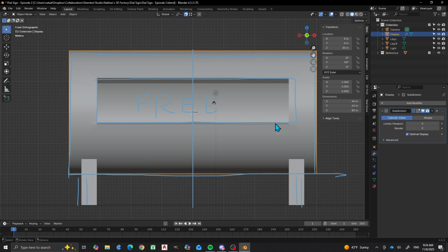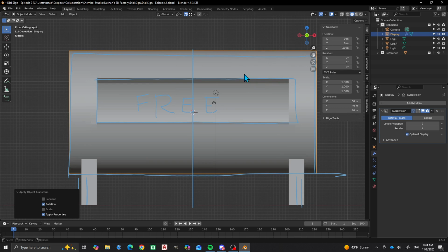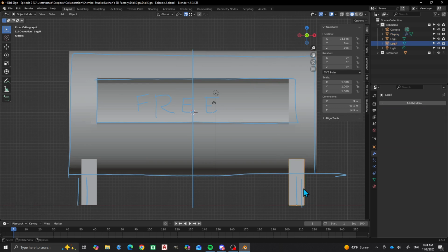Now I'll get a basic shape for the drum. So it'll be another cylinder. So this cylinder right here. Oh, and you'll also see that this has a 90-degree rotation. I don't want that. So I'm going to do Control A, rotation. Now it's at 0. Okay, so all these are at zeros. All right, so that should be good.